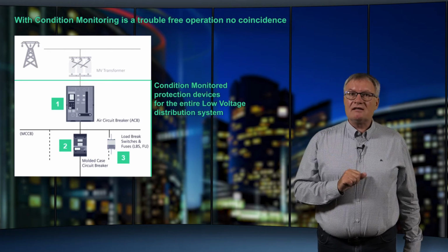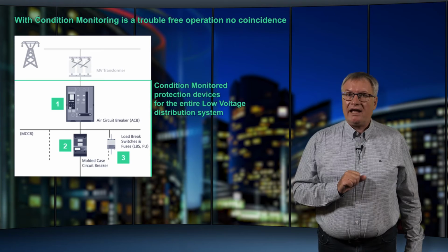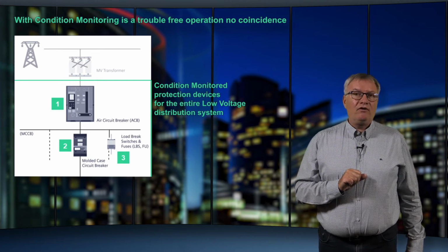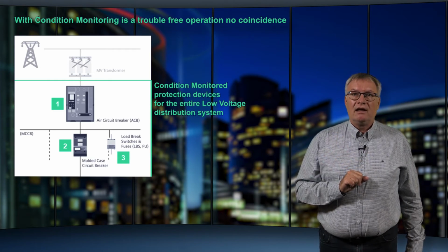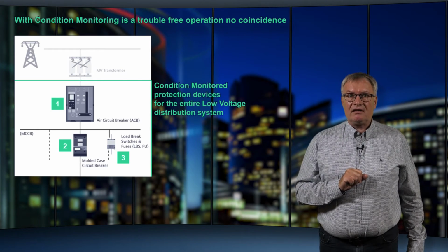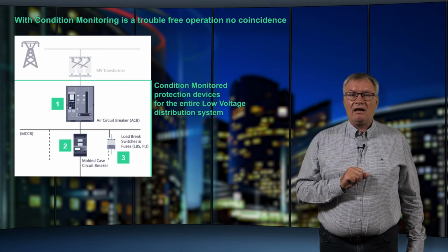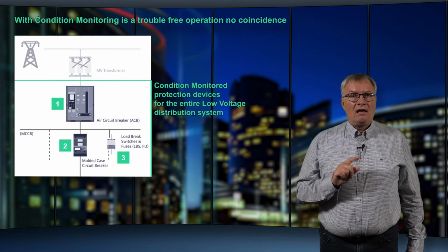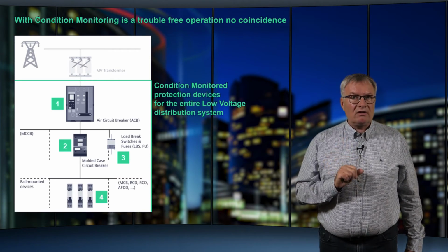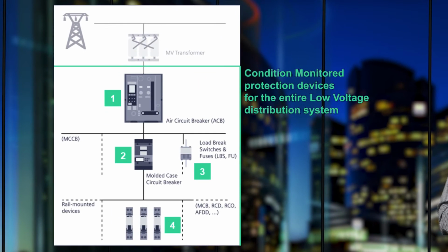The situation is similar with communication-capable HRC fuses, which offer excellent protection. Fuses have no aging impact if operated within their operating limits. Therefore, an integrated current and temperature monitoring is the best way to avoid a creeping fuse failure. Even classic modular installation devices constantly monitor current and temperature. They offer optimum protection against changed or unclear load conditions.